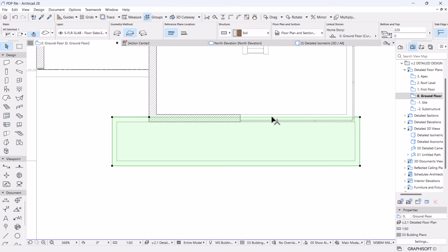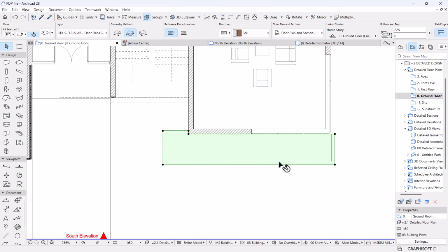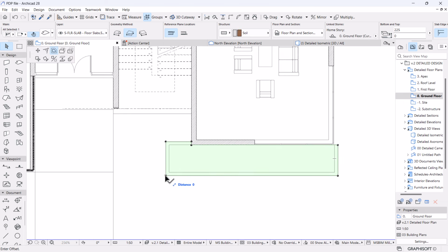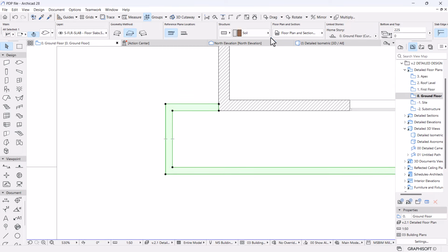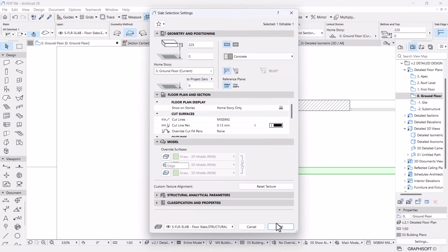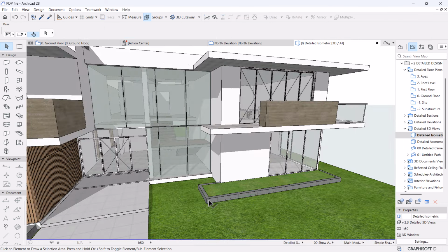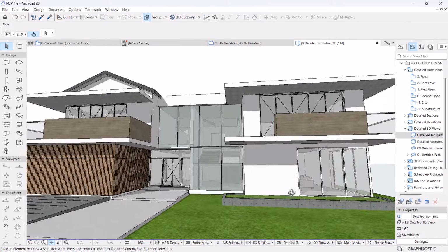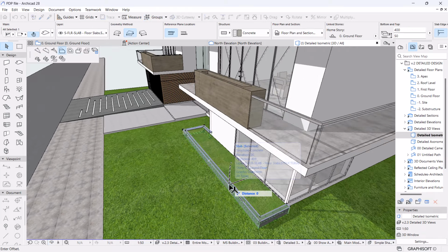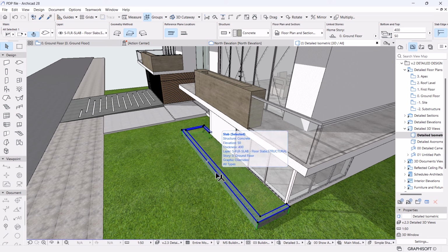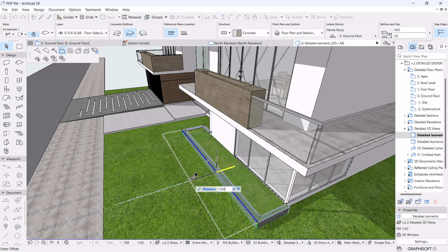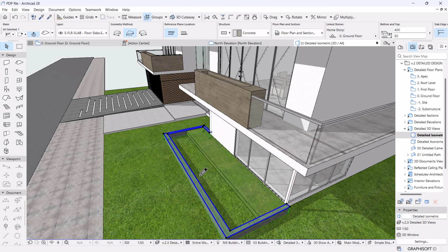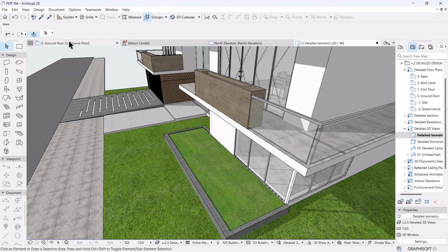on this point. Then I can get rid of this material here. Okay, and I'm going to select this, subtract using the internal soil, then change this to concrete material, and get rid of the surfaces. Check on 3D, set this to be 400 height and plus 50 a bit. Perfect. It was supposed to be in line with the balcony. I don't know, or if not, maybe 1.2, something like this.